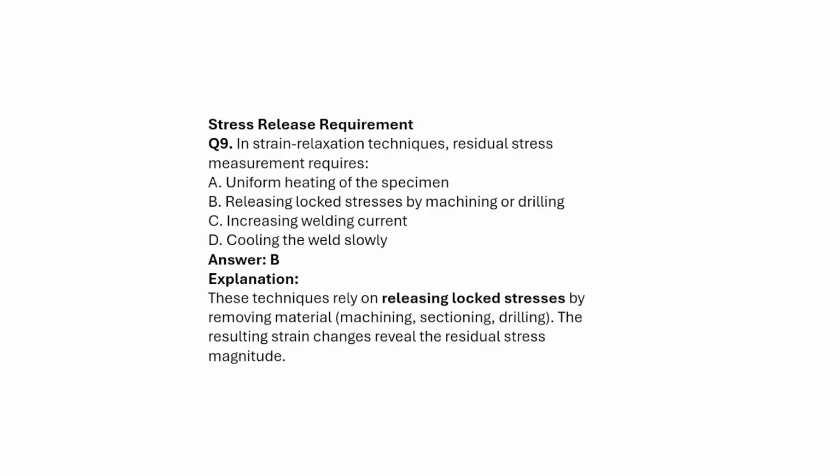Answer will be B. We have to drill the hole so that the stress relaxation takes place. This technique relies on releasing the locked stresses by removing the material by using drilling, machining or sectioning. The resulting strain changes reveal the residual stress magnitude.